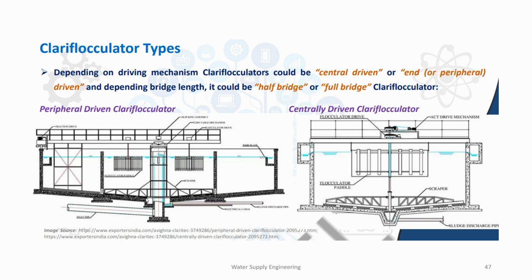So there are different types of clariflocculators depending upon the driving mechanism. That is, they can be either central driven or end driven, and depending upon the bridge length, they can be half bridge or full bridge. So there are two different classifications for clariflocculators. One is based on the driving mechanism, and the other is based on the bridge length.